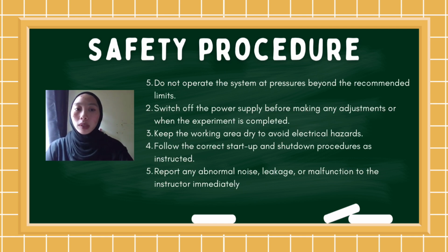Six, switch off the power supply before making any adjustment or when the experiment is completed. Seven, keep the working area dry to avoid electrical hazard. Eight, follow the correct startup or shutdown procedure as instructed. And lastly, report any abnormal noise, leakage, or malfunction to the instructor immediately.